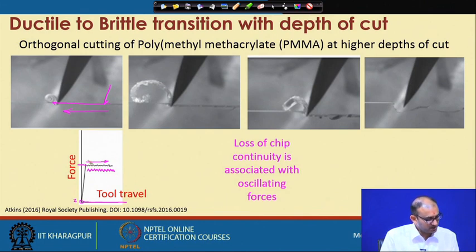Let us consider this one as a reference signal, a small signal, and we are not getting any disengagement between the workpiece and the tool, because the tool is in full contact with the workpiece throughout the cut. Whatever variation is there occurs for many reasons. The machine structure plays an important role, vibrations occur, stiffness of the machine tool is important, and the cutting mechanics and the material you are cutting also create this signature. We will discuss this in more detail in the sensor part, but for now let us consider this variation unavoidable.